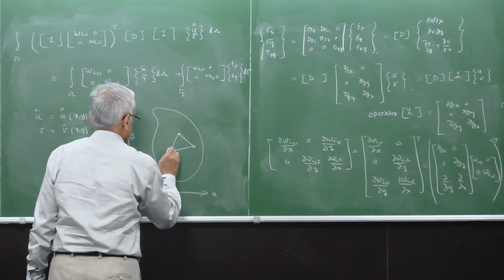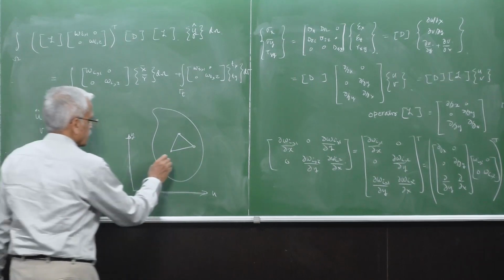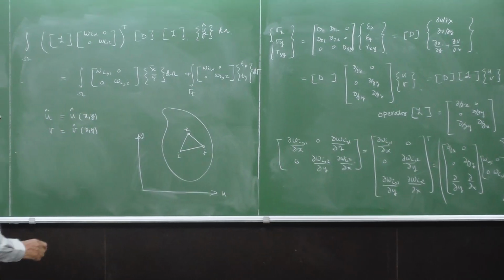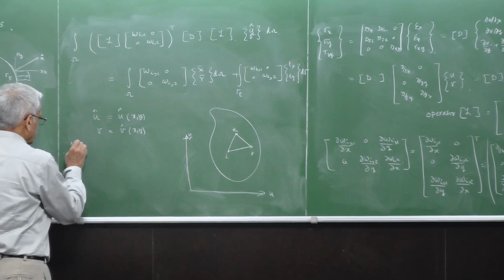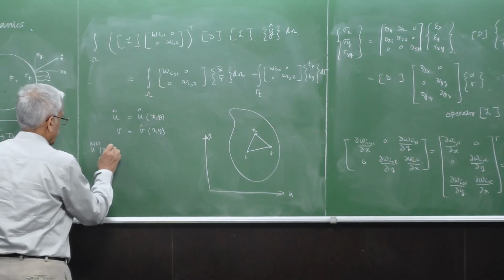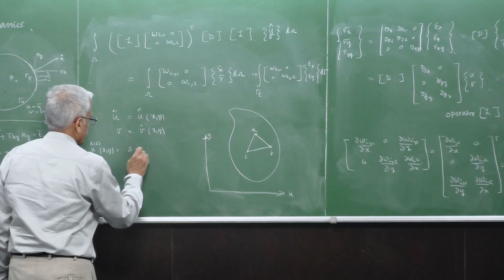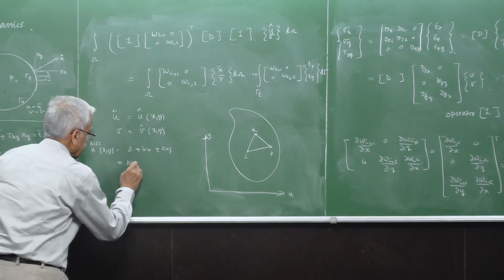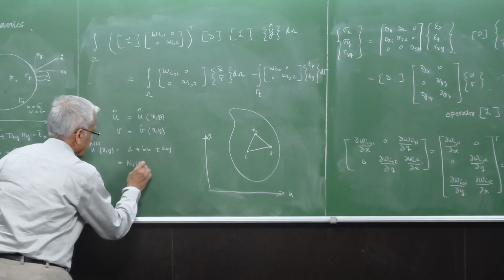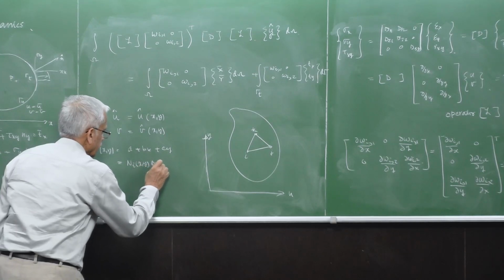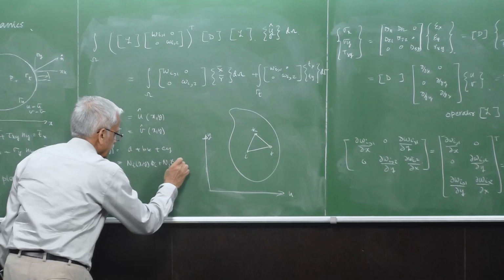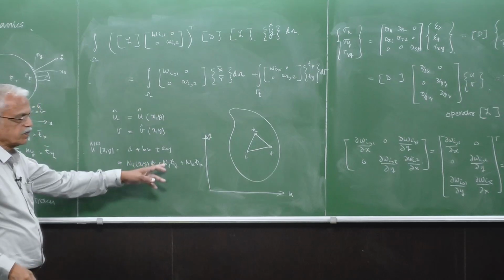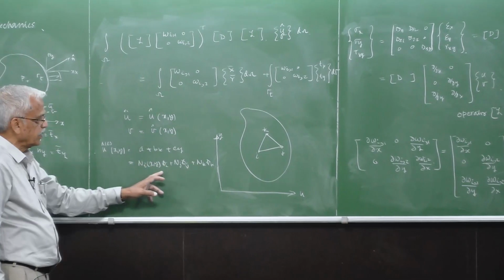This also we have done in the case of the heat conduction problem. So a triangular element with 3 nodes like this one will be, for example, u, which we write as A plus Bx plus Cy, which is equivalently written as Ni phi i plus Nj phi j. So this is straight away in terms of polynomial terms, whereas this is in terms of the nodal values.